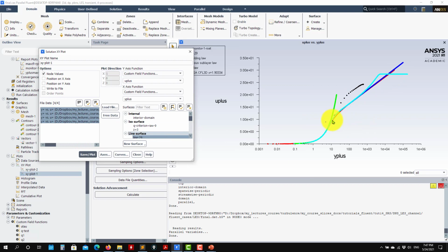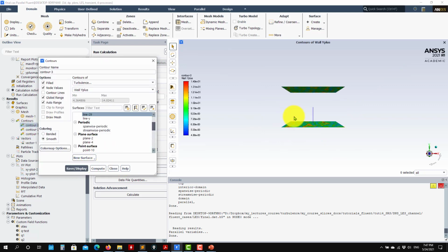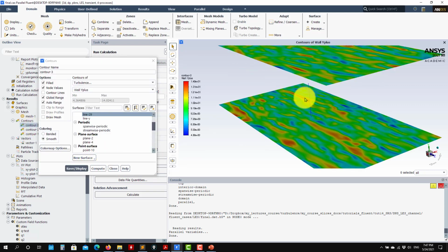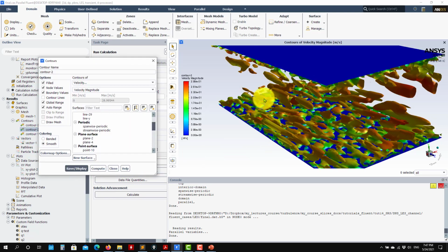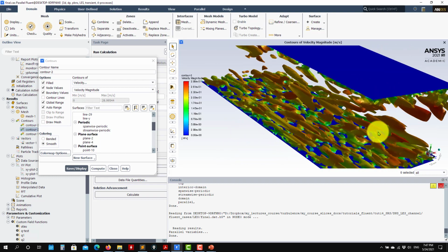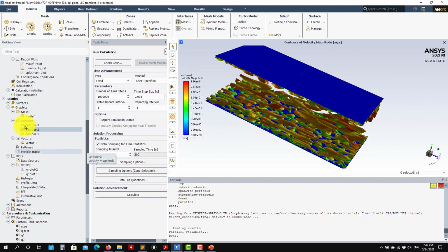So you recall the DNS. The DNS was kind of trying to fit this one. See, this one is now midway between this and this. Okay, so again, this is the model kicking in close to the wall, but still the mesh is not good enough. Okay, so if we plot here, see, basically we're sampling here, but the mesh that we have in this case is not good enough to resolve well all these structures and everything. So that requires some refinement in the mesh.